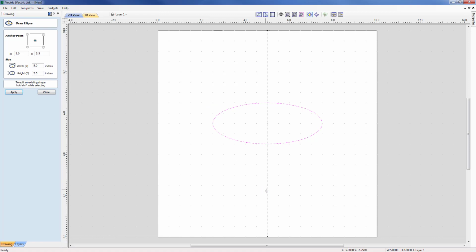Okay, similarly now if I wanted to specify maybe just the height, so I'm going to specify my width. Okay, so I'm going to get that roughly right on. Okay, it's going to be 7 in width. Okay, but I need it to be a height of 2. Then I can just hit 2y, and that will have the current width in X, but with the height that I specified through the keyboard.